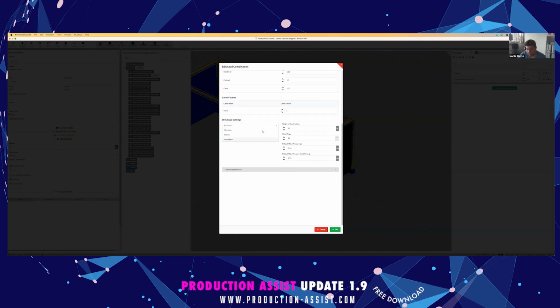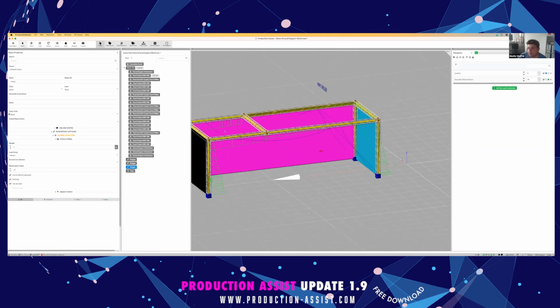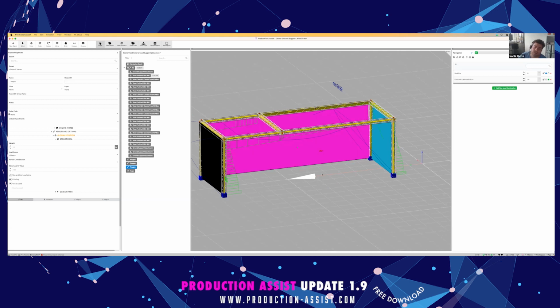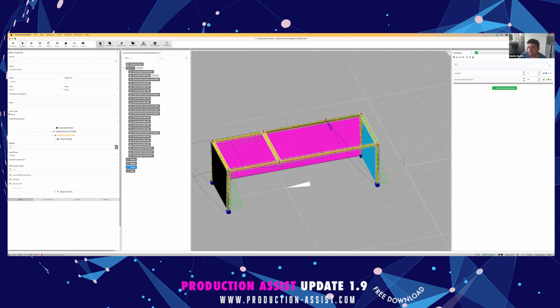What is built in by default is the wind load zones from France and Germany, which you can use to get the right wind pressure values for your calculation. All of this together allows you to calculate any amount of wind load that comes to such structures and define it really easily by just drawing polygons. That's the first thing with the wind load planes.